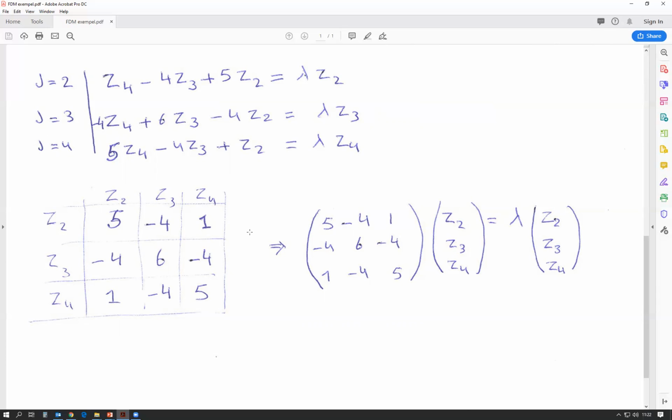In my licentiate thesis that I did in 1996, I analyzed cable-stayed bridges in a dynamic vehicle-bridge interaction problem that we will talk more about on Wednesday, using the finite difference method, idealizing a cable-stayed bridge with a beam on elastic foundation and analyzing it in this way. So you can do quite complicated things with the finite difference method.